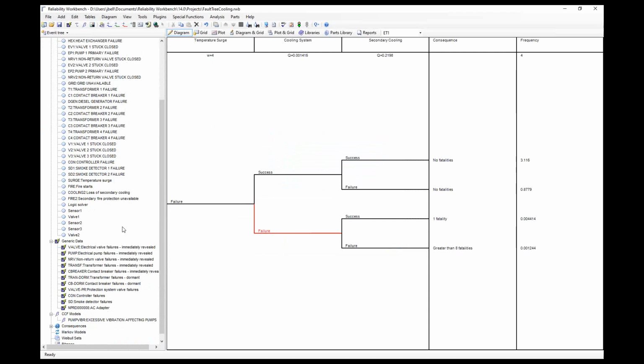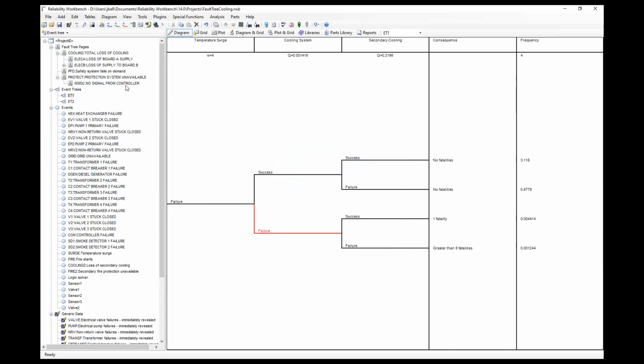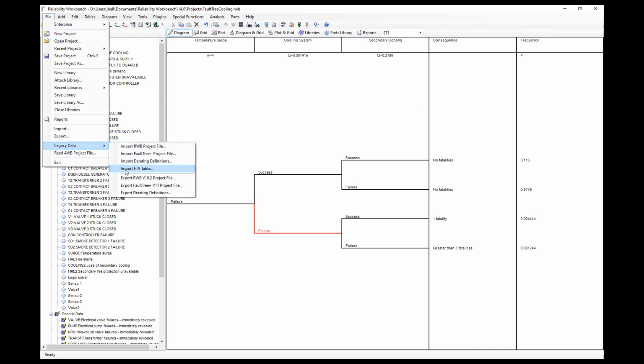If you have a bill of materials in an Excel spreadsheet, just go ahead and import that. You can import a spreadsheet. If you have a list of all the events, all the components in your system, you can import that events list. You can even go so far as importing the fault tree. That gets a little more complicated because you have to somehow define the connections and the relations between everything. That's a little bit harder than just a list of items, because now we have to link them all to each other. But even that can be done, and we even have special features for importing certain fault tree tables. If they're formatted in a certain way, we have processes for importing a fully formed fault tree into the tool.